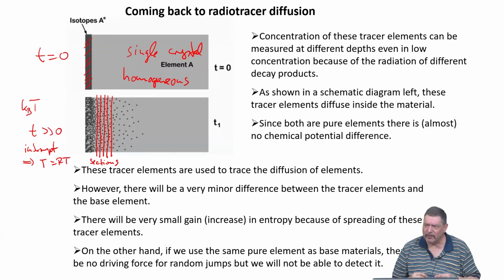This is the reason. Another reason is if we now add different atoms inside of a system, and also isotopes are different because the mass is different, right? If you add too high concentrations, you could change the local structure. So the diffusivity might be affected by adding these atoms into the structure. And then you'd get a result which is not really relevant for the pure material without these isotopes in high concentration.